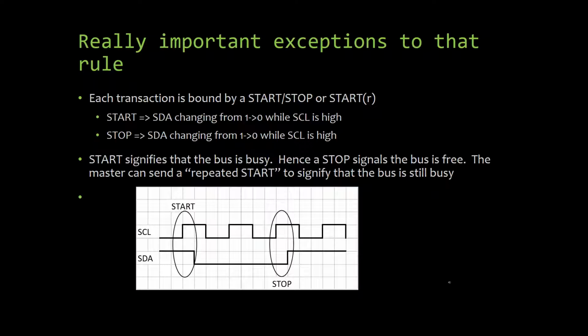Start takes on a different meaning too. It also signifies to all the other masters that the bus is busy, and a stop signifies that the bus is free. If the master that currently has control of the bus wants to send a repeated start, he can signal that and keep control of the bus.